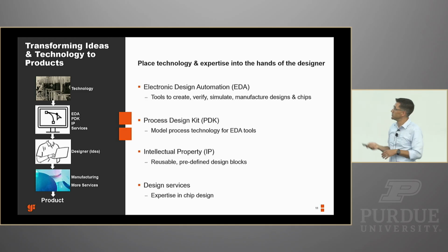But what is critical within that as well, and this is a domain I've been primarily involved in over the years, is the PDK, or Process Design Kit. So the PDK is a set of files, models, decks, and tech files that describe a given technology. If we're talking about silicon photonic technology, for example, it would have a PDK associated with it. And that would have all the necessary information for these EDA tools to be able to provide the designer with information about, are they passing the rules that will allow them to manufacture with us? Are they meeting the performance they expect to see? So this is what the PDK comes in as, a foundry deliverable that is then married with these EDA tools to give that insight to the design teams.